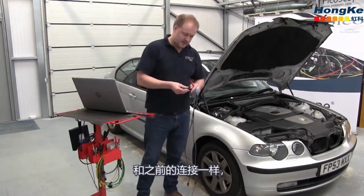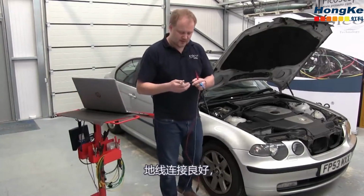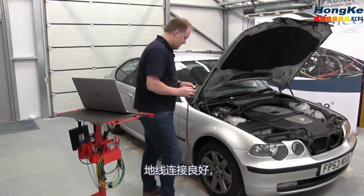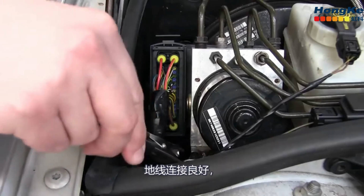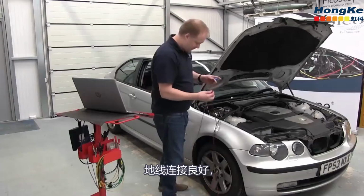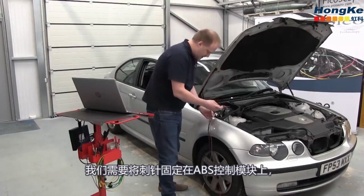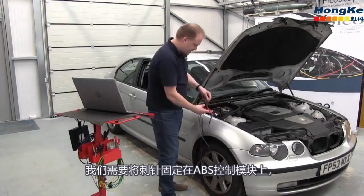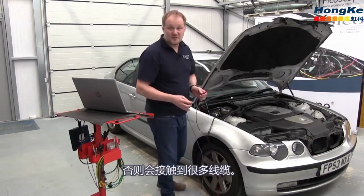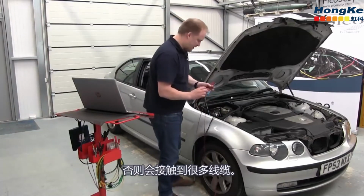So back to the same connections, no different. We've got our earth fly lead. Again, we've got a lovely earth connection available right at our fingertips, and now we need to back pin on the ABS control module. Obviously there'll be a lot of breakout leads involved otherwise, so we'll back pin.